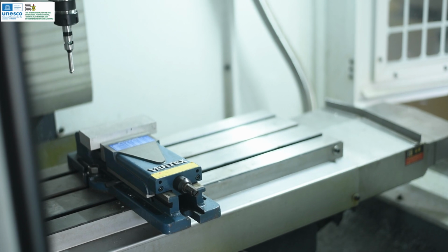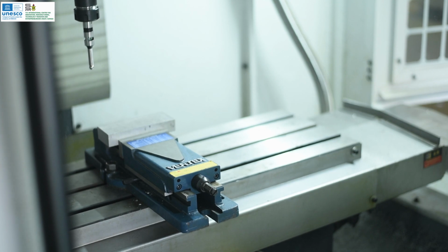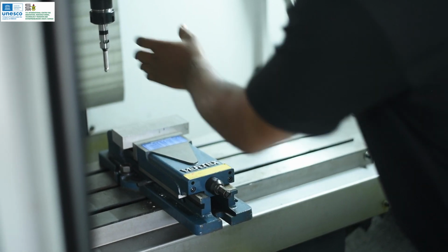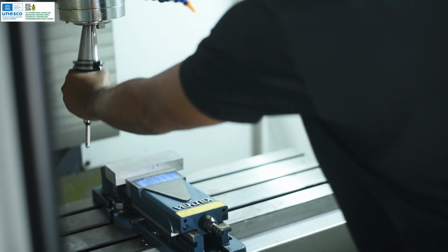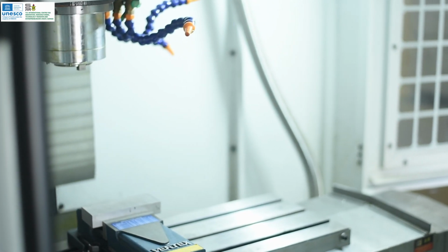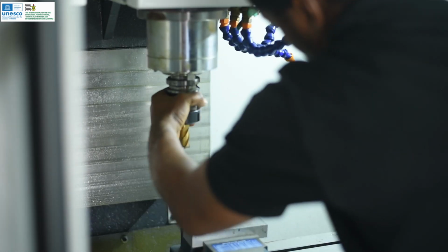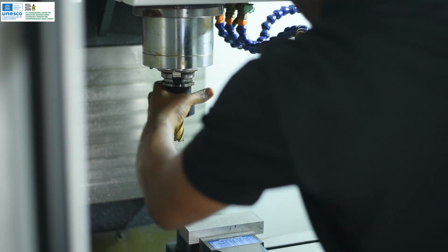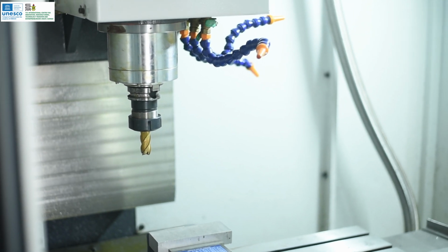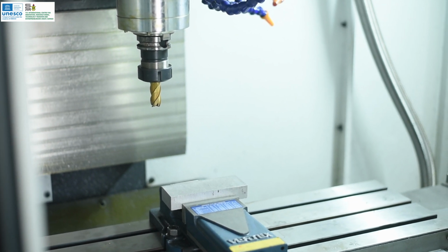This assumes that you do not have all the tools required to find the surface of your workpiece. So to do that, we're going to start by removing our edge finder. And the edge finder is gone. Going to replace that now with our end mill. So we're going to insert an end mill. Always make sure your tool is secure. And we're going to jog now our axis. So while in manual mode, we're going to jog our axis.